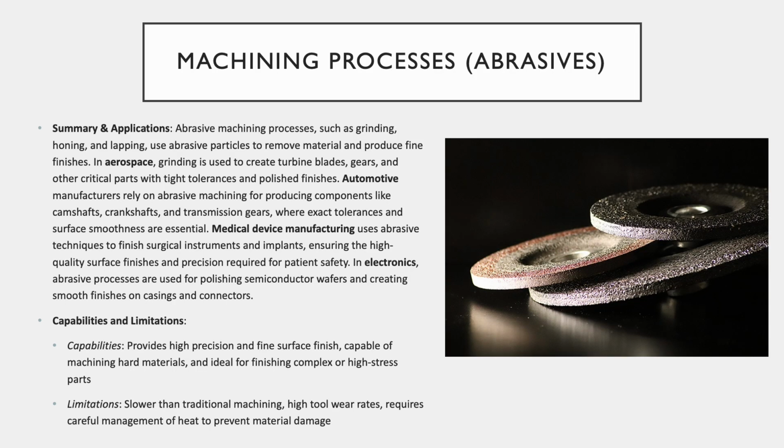Lastly, I'm going to talk about abrasive machining processes. Processes like grinding, honing, and lapping use abrasive particles to remove material and produce fine finishes. Within the automotive industry, manufacturers rely on abrasive machining for producing components like camshafts, crankshafts, and transmission gears. Medical device manufacturing uses abrasive techniques to finish surgical instruments and implants, ensuring high-quality surface finishes and precision required for